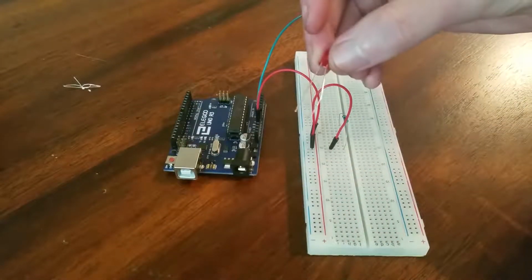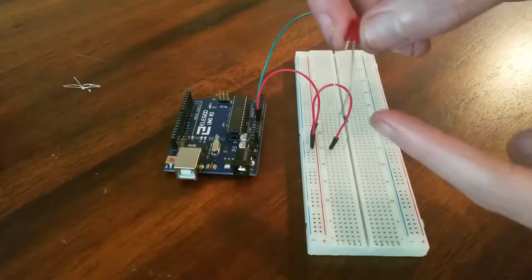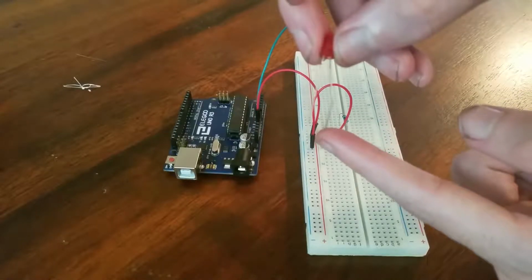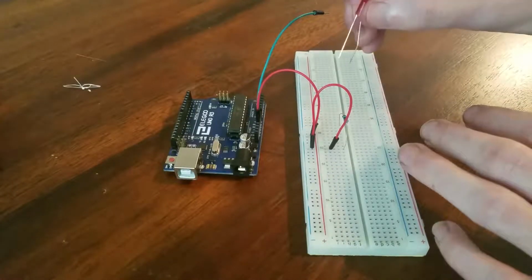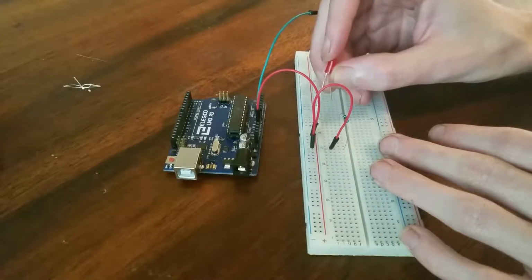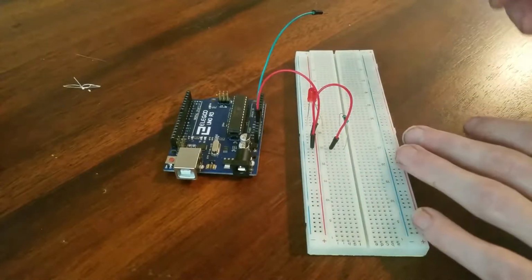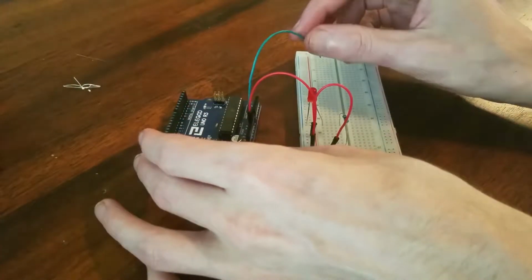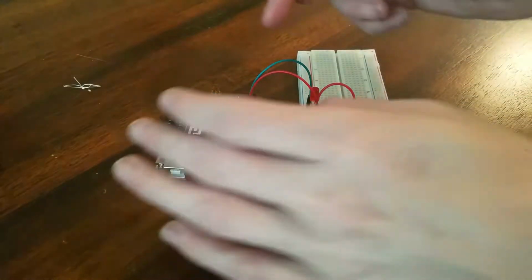We're going to take our LED, remembering that the positive side, or the side that the voltage is coming from, is the longer side. So from the resistor, we're going to go the longer side and then the shorter side. We're going to put the shorter side on the blue rail on the edge of the breadboard, and the other end in line with where the resistor is. Finally, we're going to complete the circuit by plugging back into ground into the Arduino.